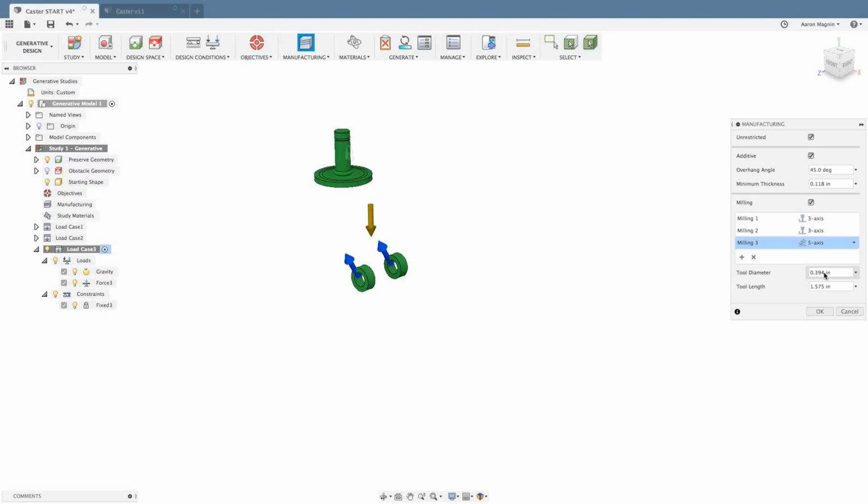So the other thing to consider when you're doing this is to determine things like the tool diameter. And what you're thinking about there is not your roughing tool, right? You're not thinking about your face mill. You're thinking about when you're going to finish this thing, what tool diameter is essentially the smallest that you'll be using, and this is something that you'll be able to define here. And we're looking at ways of improving definitions here and adding more abilities so that it's going to consider more information about your machines as you get into using this.